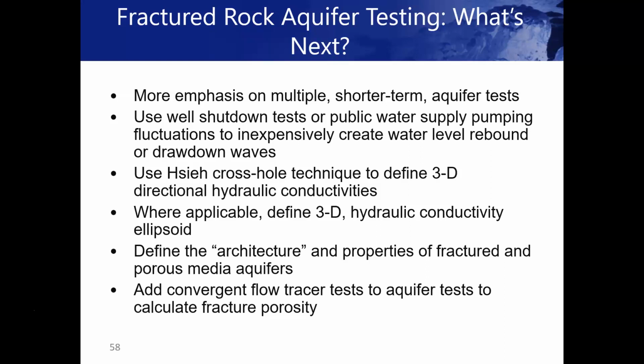as you pump the well, you will begin to draw down water levels in the well, which will go lower than some of the water-bearing fractures. So as you're pumping the water level down, let's say water-bearing fracture A is below the water level in the well, and the amount of water that's flowing out of that fracture will be a function of the water level in the well. But once the water level reaches that actual water-bearing zone A and starts to fall below it, the water will still be coming in, but it'll no longer be a function of the elevation of the water in the well because it's dropped below the fracture. So it'll continue to drain out and may eventually reach kind of an equilibrium seepage rate into the well, or it may dry out.